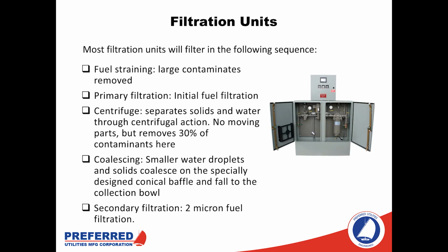Now, the skid that we talked about very early on, that's not part of fuel transfer, but it is critical to the system as far as maintaining the fuel, is our filtration unit or polishing skid. Now, this unit is actually becoming more important as time goes on because we have systems that are larger stored fuel. We have things like ultra low sulfur diesel, which can contribute to long-term fuel storage issues. So these are becoming more and more important. And as I mentioned before, it's not just about filters and strainers. It's also about having a stage like a centrifuge or a coalescing stage where we're actually pulling water droplets out of suspension in the fuel, removing the water from the tank, because the water itself is going to be a major driver of fuel quality issues.